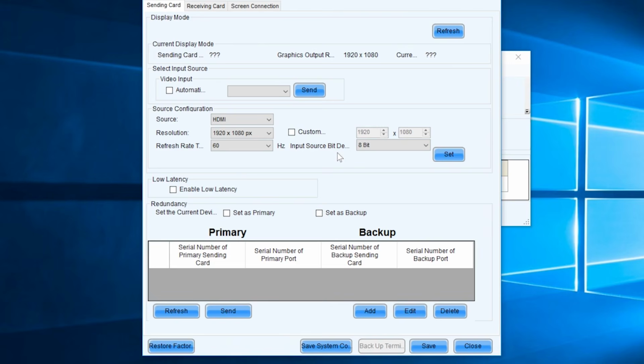So the media input, that's what this is coming up as. If this was incorrect, I would go through and on your sending box try and change the resolution, as opposed to changing the resolution on the NovaStar itself, because then you'll have a mismatch of resolutions.